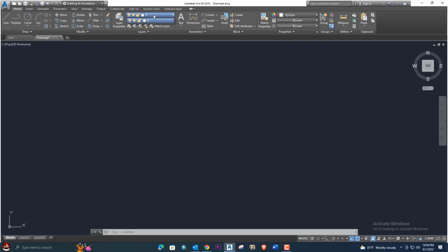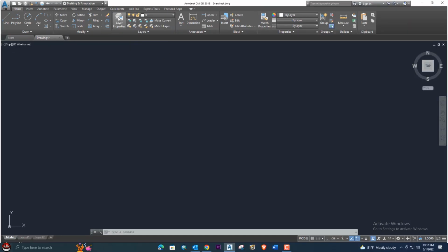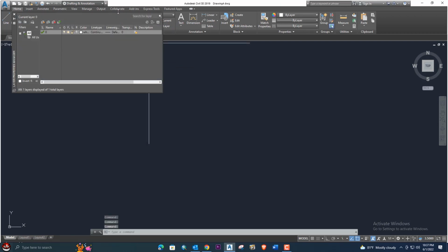And next, we will add some layers because we will play with different objects for easy classification. And we'll add different objects to different layers. Let's start by creating layers. Go to the property from here, select this property, click here and this pop-up menu will open. And now we will go to this option, new layer, create new layer, enter.